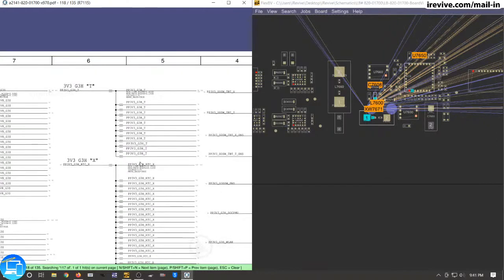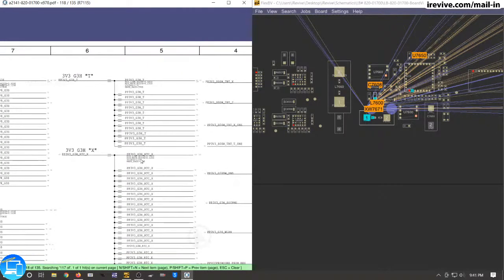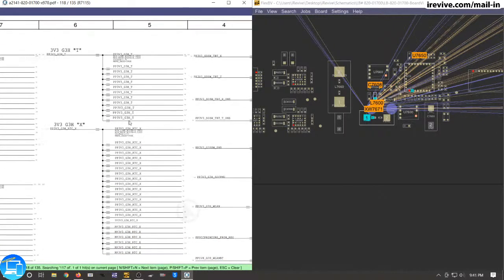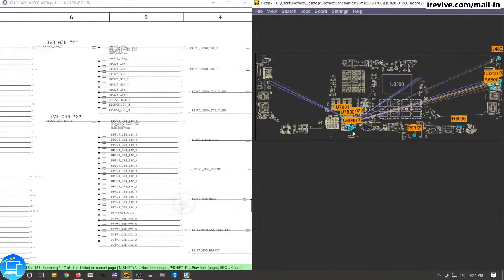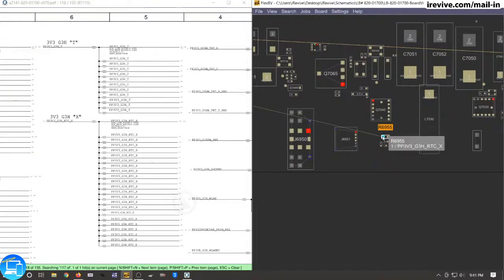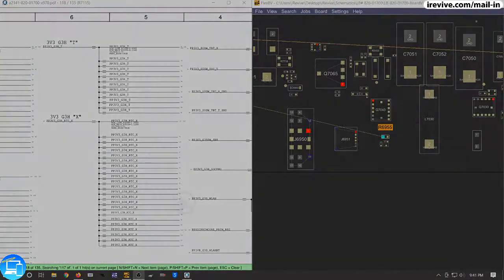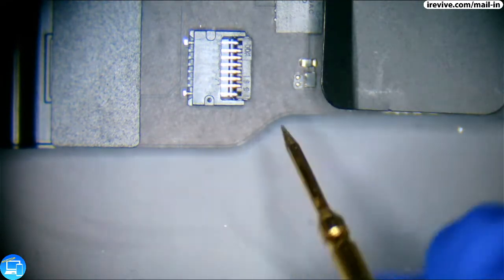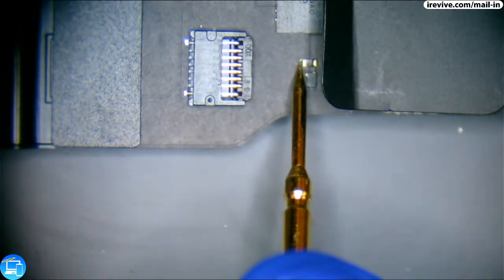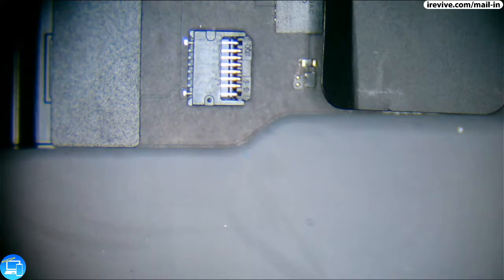And we know that we have our PP3V3 G3 hot line present because that is how we are turning on our CD3215s. We can just confirm that real fast by probing this resistor right next to our battery connector. It's kind of tucked all the way over here, but I think we can reach that. Yep, 3.3 volts, which would make sense because 3.3 volts is necessary.